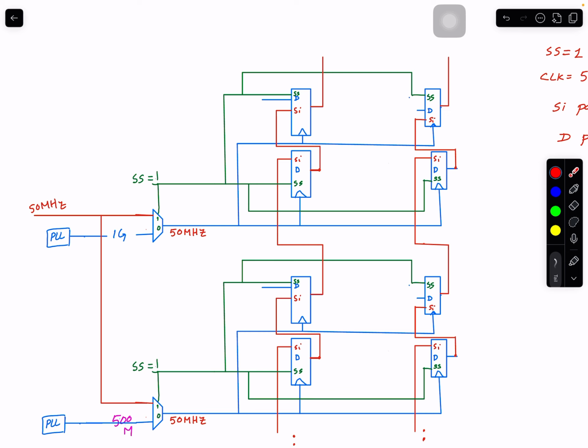I'm not modeling this exactly like our functional scan shift would be, but there could be some logic which only works on that particular clock, not the other one. And you want to also make sure that one is timed at frequency. But overall, your goal is making sure that however you're going to use your silicon, that is modeled in your pre-silicon at this moment.